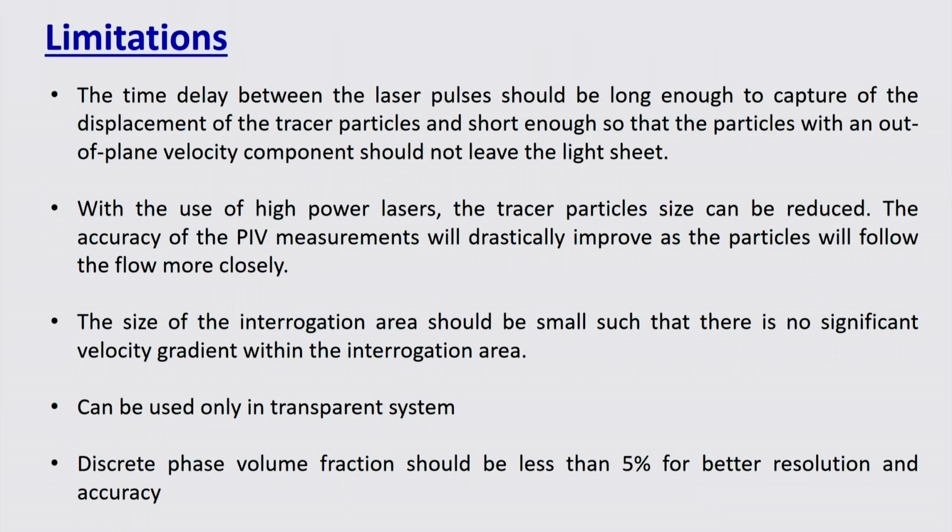So, the laser pulsing rate should be very accurate. You need to be careful about that. Then you also have to consider the power of the laser. You need a very high power laser, so that you can reduce the particle size, as I said, but the problem with a high power laser is that it is very costly and there are safety issues also. And then the size of the particle should be small enough so that it can follow the path of the fluid.